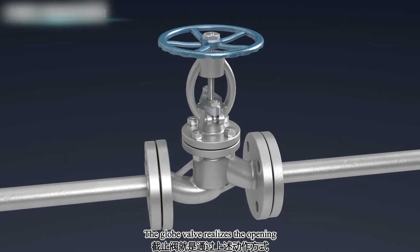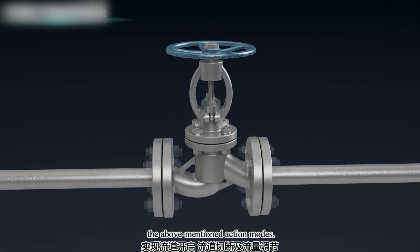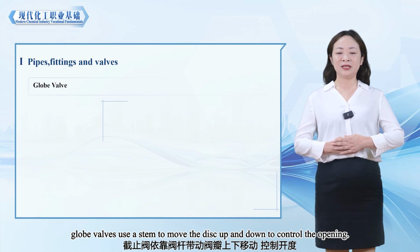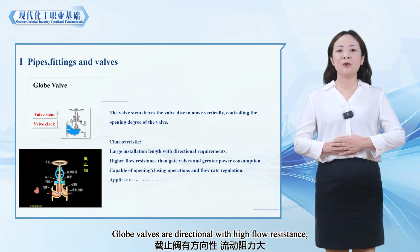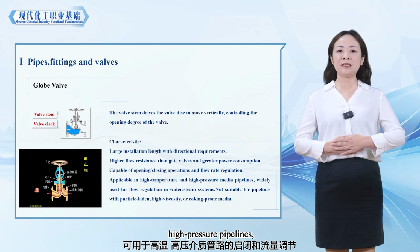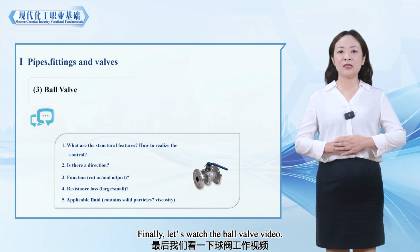The globe valve realizes the opening of the flow channel, the cutoff of the flow channel, and the regulation of flow through the above-mentioned action modes. Through study, we see that globe valves use a stem to move the disc up and down. To control the opening, globe valves are directional with high flow resistance, suitable for shutting off and regulating high temperature, high pressure pipelines, but not for media with particles or high viscosity. Finally, let's watch the ball valve video.